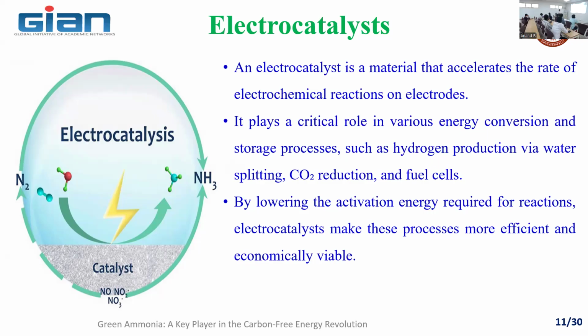You also need to select a catalyst, maybe noble, and you can also find some catalyst which is lower in cost. Because the amount of catalyst you are going to use is not a few grams; for ammonia generation in terms of tonnage, we go for a few tons of catalyst. So the cost you are going to invest for buying the catalyst also plays a major role. So you need to do some kind of study in catalyst selection.